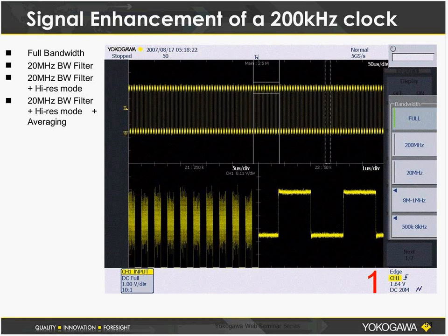We're running at full bandwidth. And if you look at the zoomed-in portion on the bottom left, you do see some banding. That banding shows you almost like different areas of intensity. That banding actually corresponds to quantization noise. So each of those bands is exactly one LSB, or one quanta, of the 256 steps that are available in an 8-bit converter. So that's the typical resolution that you'll see in an 8-bit scope from any manufacturer.